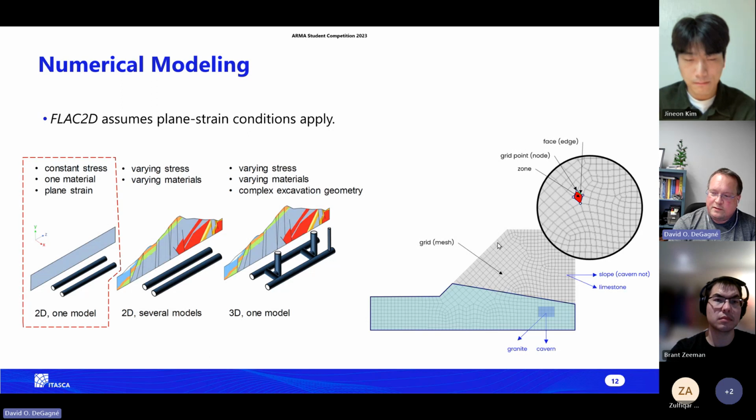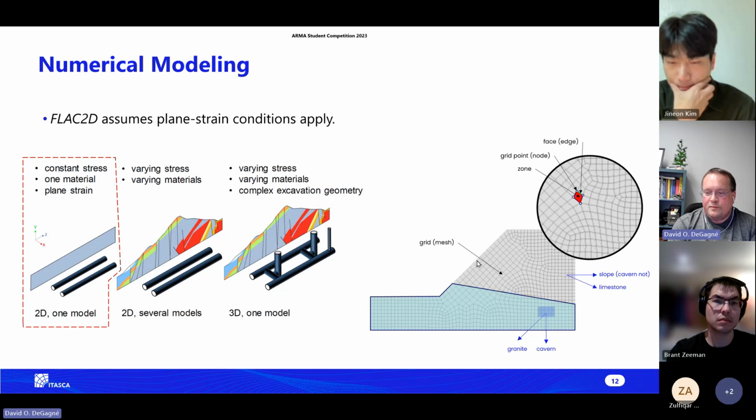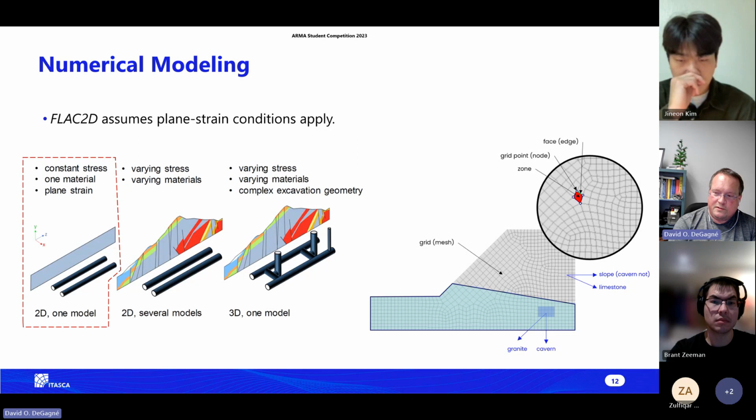However, in a large strain model, these points, say for example along the pit face, are free to actually physically move, and their location will be updated as displacements or velocities change. And in this case, we'll see when we look at the template that we will be running primarily as a large strain model. So we'll actually see the deformation and physical movement of the face of the backfill in the stope, depending on the strength of the material.